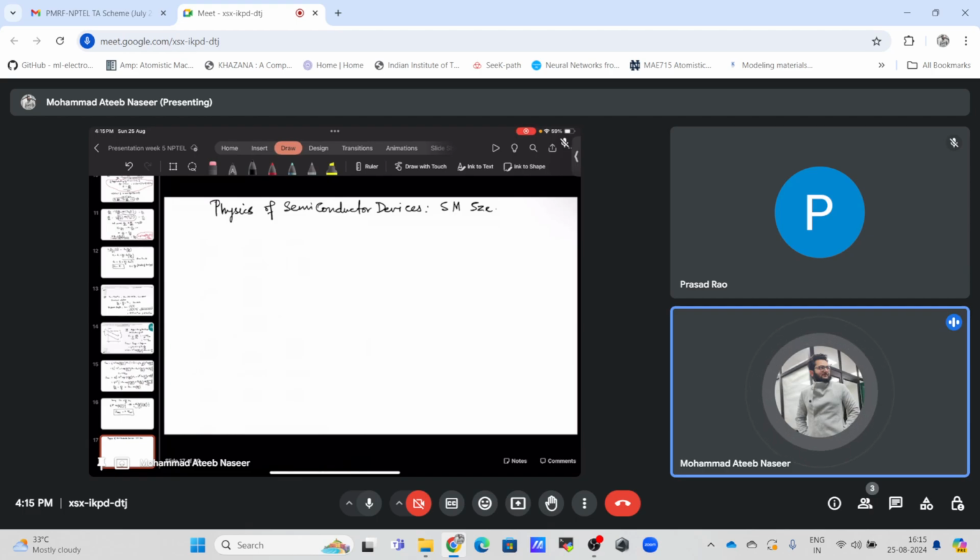And also we know that the Fermi level of the semiconductor can be changed by doping the material. So as a result, the semiconductor material has a variable work function, which depends on how much we are doping the material. But the electron affinity is simply the distance between the vacuum level and the conduction band edge. So this will never change for any semiconductor. This will always remain constant. So electron affinity is unique for every semiconductor. And the metal has the work function, which is the difference between the Fermi level of the metal and the vacuum level.